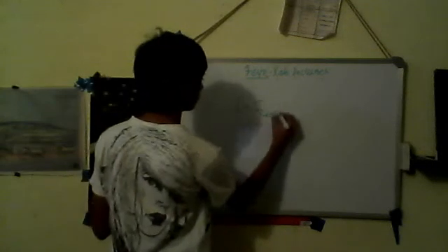However, it's a long one. So I is equal to I_COM plus m h squared. Here I_COM is the moment of inertia about the center of mass, m is the total mass of the body, and h is the perpendicular distance between the given axis and the axis through the center of mass.